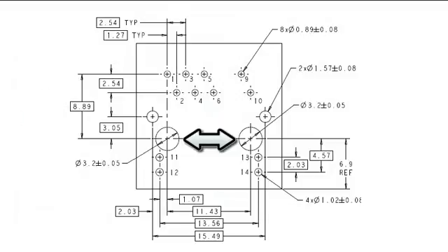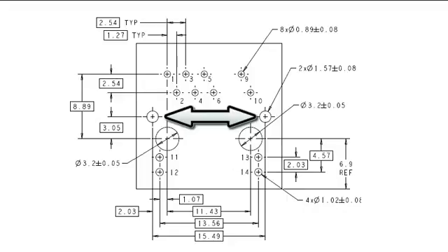The first pins I'm going to place are going to be the mounting holes, and that's because so many of the other dimensional references are to the mounting hole locations. Note the dimension 6.9. That's going to give us the offset of the mounting holes from the body edge. Also looking at the pin numbers, you can see the last pin number given is 14 for one of the LEDs. So we'll start with 15 and 16 for the shield pins, and then 17 and 18 for the mounting pins.